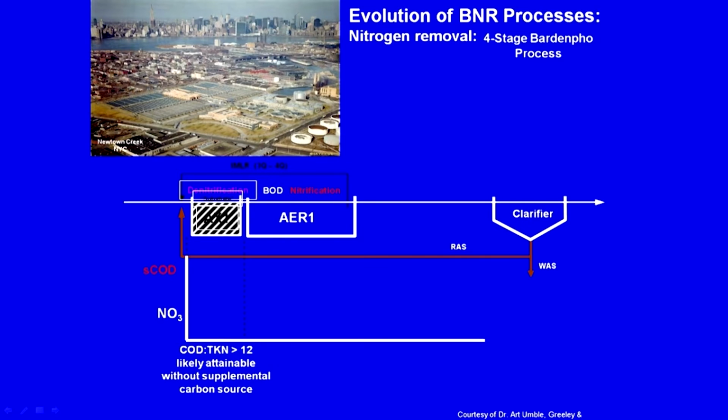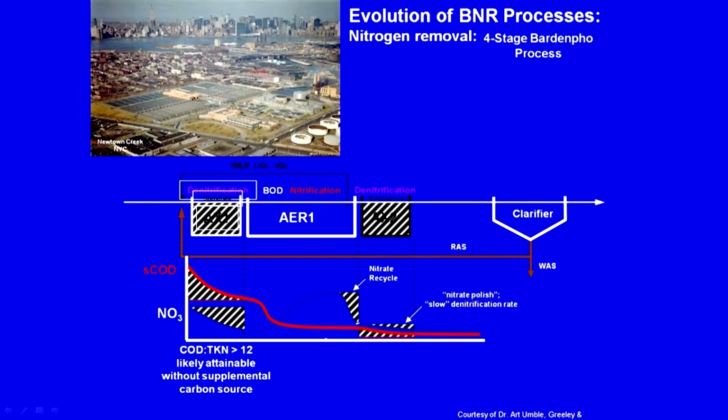This is more or less the same as what we had earlier, right, internal recycle and the general sludge, let us see. But what else? Again we have a denitrification second anoxic tank. So, what is going to happen? Similar profile until now, and here you have further denitrification, right. So, this level of nitrate is being removed because you have a second denitrification tank, let us say, so a nitrate polishing tank. Earlier you had only the one anoxic tank before aeration, with pre-substrate. Now you have an endogenous one.